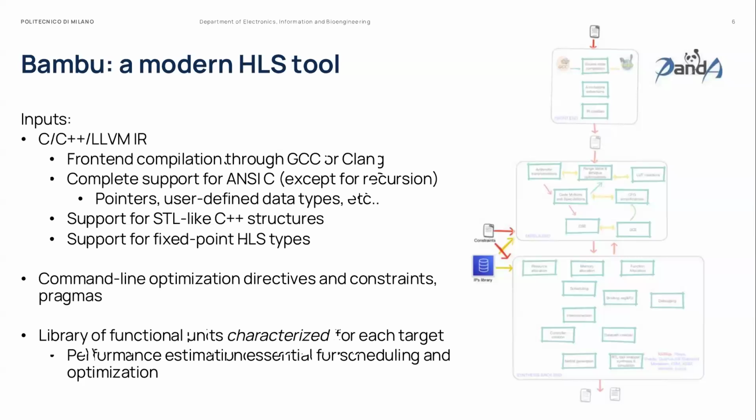So a design that has been developed for Vitis HLS should be synthesizable with Bambu with minimal modification. So one input is the description of the algorithm to be accelerated. Then we have a lot of optimization directives that can be expressed through pragmas or command line options. And you can also add some constraints on the amount of resources to be used or the clock period, the target clock period.